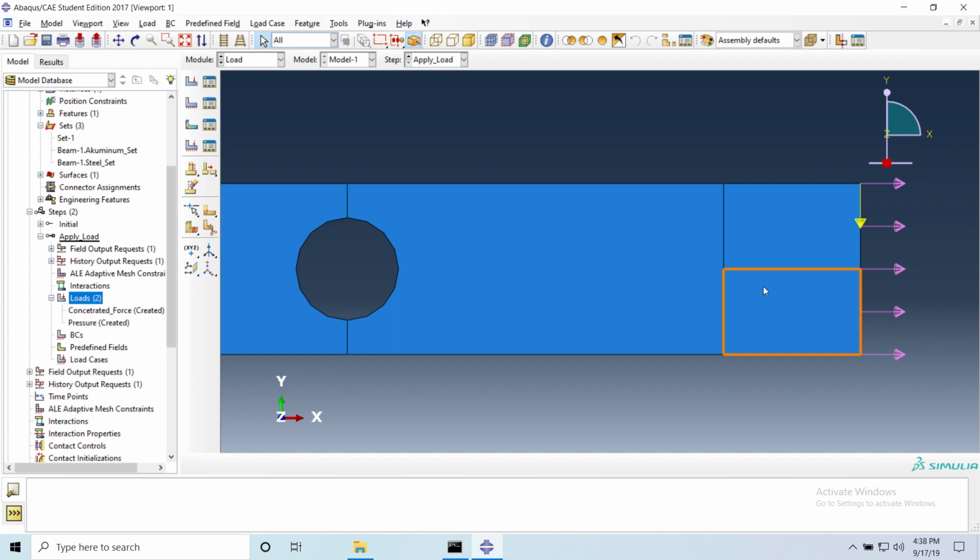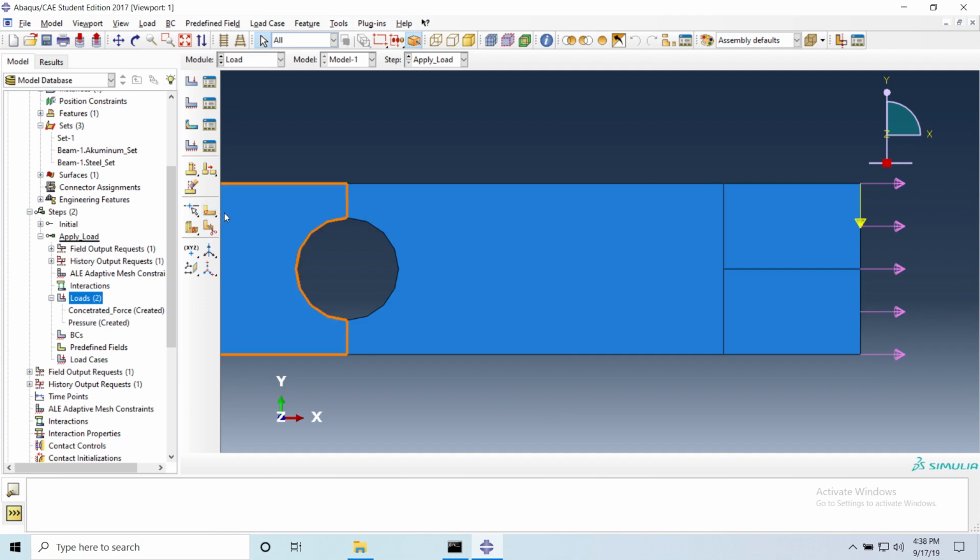And it's done in the sketch part? In the sketch, and you can also do the partitions in here. Right, so the partitions that I did, and that's a very good question, were created in the part. So whenever I bring the instance into the assembly mode, it's going to have those partitions. But now, if I only want to create the partitions in the assembly mode and not modify my base geometry, I can do the partition in here. So you leave the original untouched. But it's the same process. It's just where your partitions are created, but it's the same process of creating those.